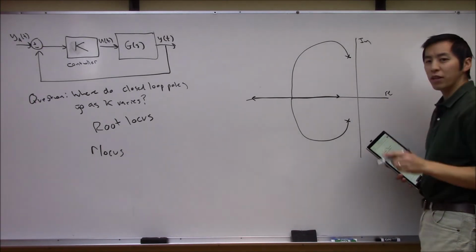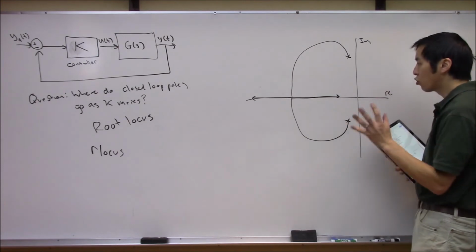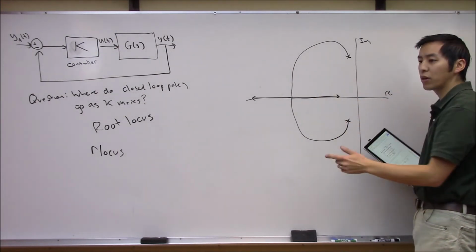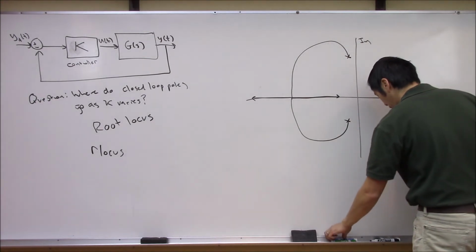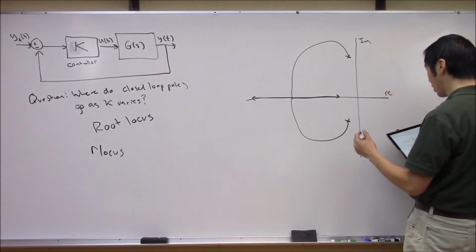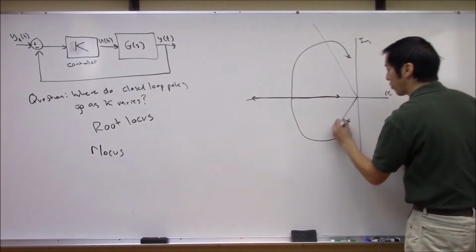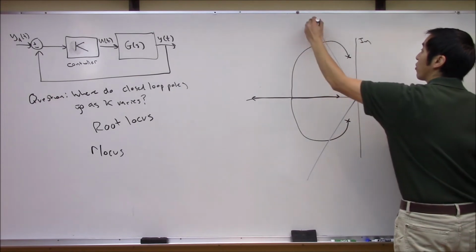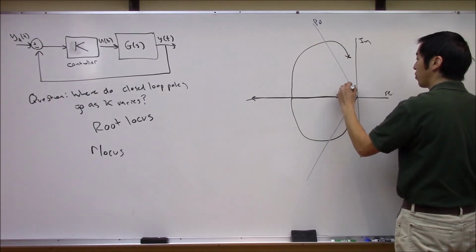If you think about this long enough, what we now want to do is superimpose over this root locus the admissible regions of the plane. We saw earlier, and I'm going to sketch this and probably do a bit of a bad job, but I think everyone knows what I'm trying to draw. Here was our percent overshoot requirement, this 62.9 degree angle.